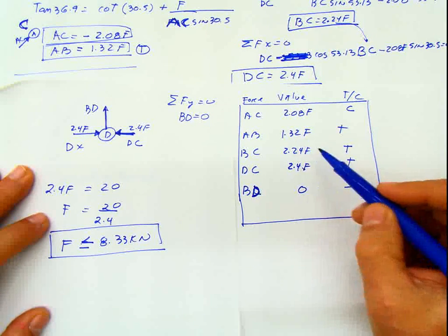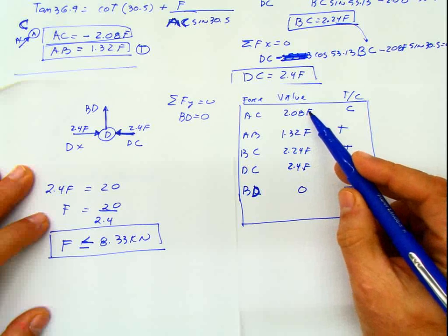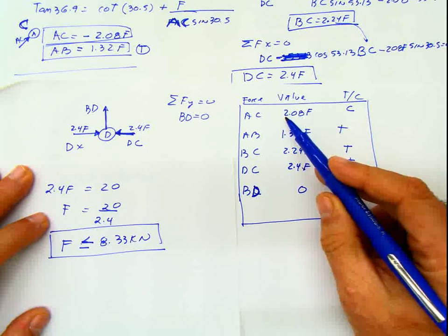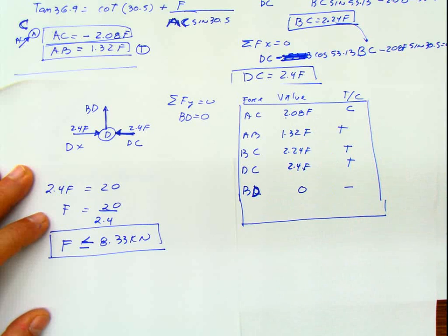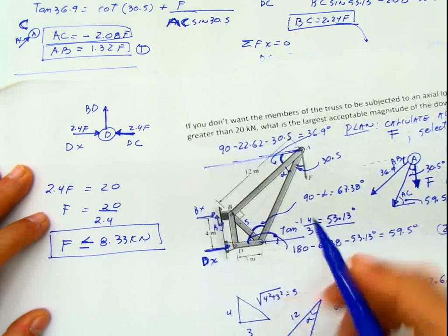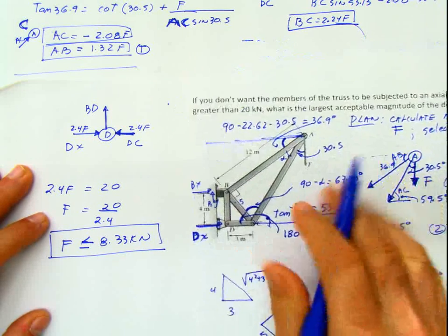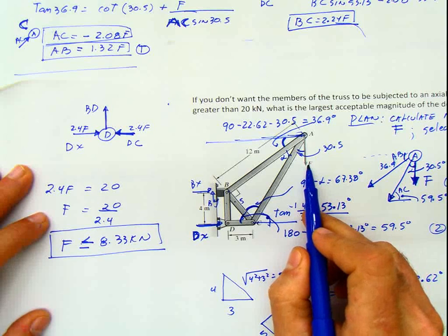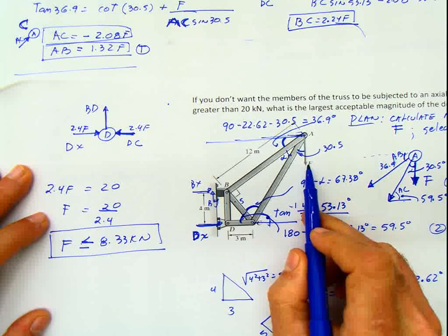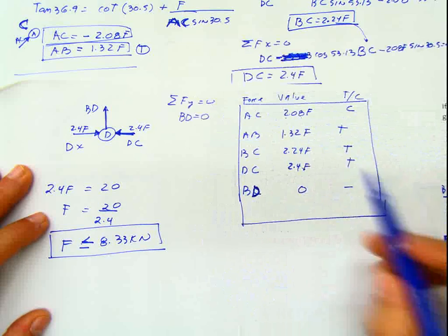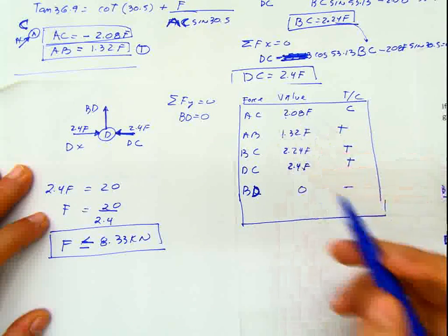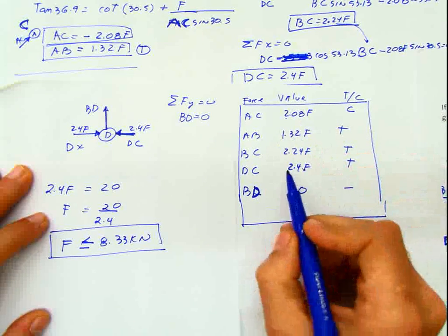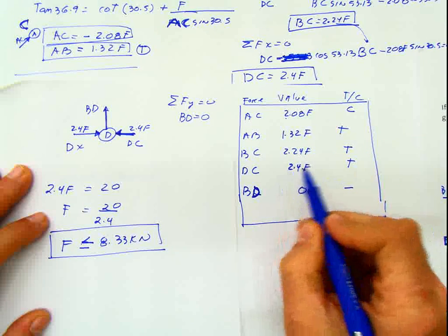And when I go back, if I put 15 here as F, this force is going to be more than 30, and it's more than 20, which is the maximum that I have. So that's why when they ask you for the minimum force, the minimum weight, that means the maximum weight that this can take, that maximum weight usually is the minimum in these ratios here. So you have to use the maximum coefficient for the maximum forces.